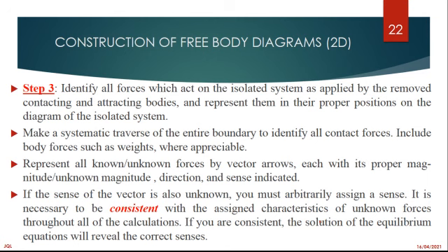What it means is, if you have forces, show those forces where they have been exerted, the distances, the direction. If it is a moment, say counterclockwise or clockwise, represent them exactly the way they are. Make a systematic traverse of the entire boundary to identify all contact faces.